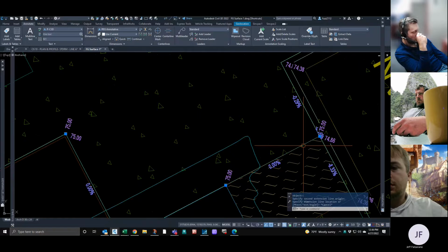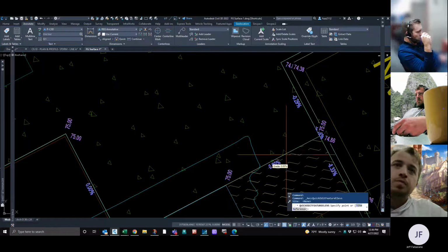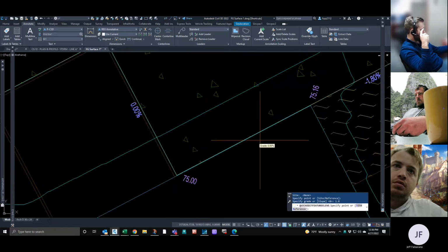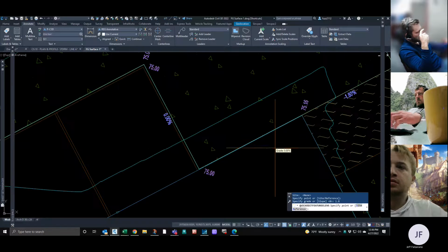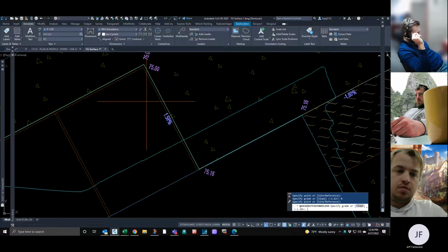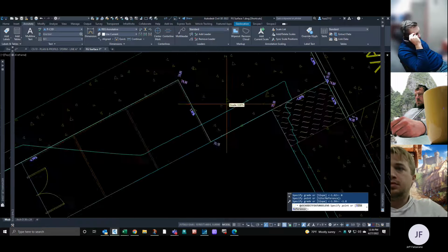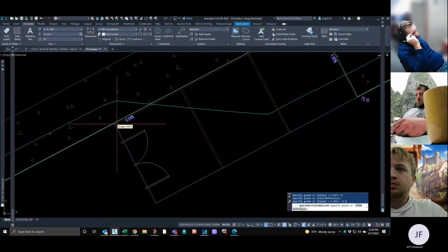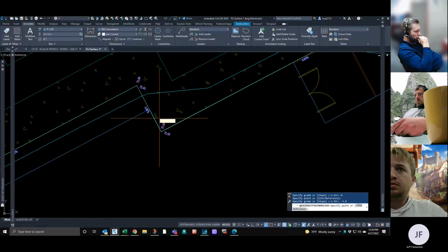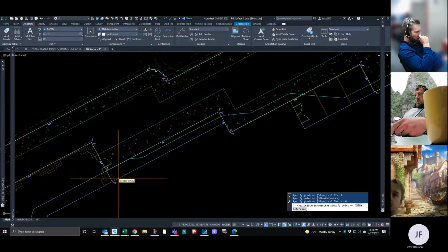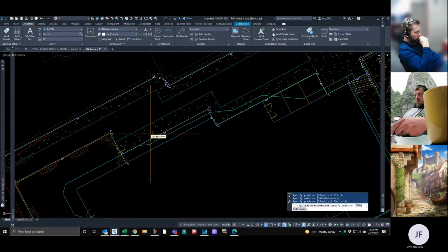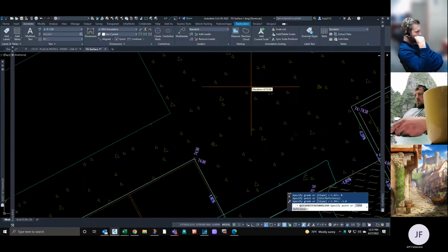So you're going to start here, edit your elevation, you're going up at 1.8%. And then you want to get to here, we can go flat in this direction, and then you're going to go down minus 1.8, and then you've got that established, and then you're just going to come back up to finished floor, and this can be probably flat, right? And then down 1.8 in that direction, and then you just got to get to this door down at 1.8 in that direction.